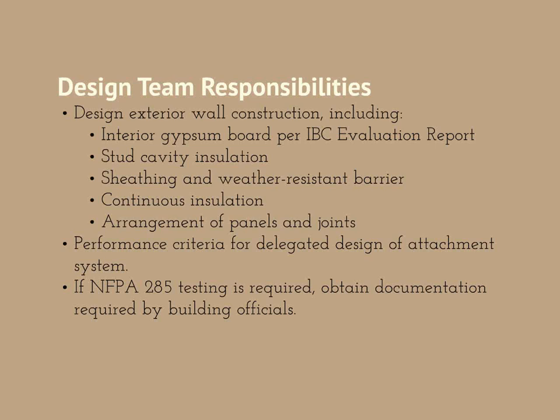But on the other hand, I want to share with the folks that I talked my firm into buying a special report on high efficiency exterior wall designs from ASHRAE, and I had to pay, I don't know, a couple $100 for it or whatever, and every one of the designs in there shows Z-girts for the continuous insulation. And so I wrote to them and said, that doesn't appear to me to meet your definition, but I think I wrote 6 different emails and received answers to 0. Well, so we're on our own. So we have to interpret it the best way that we can.